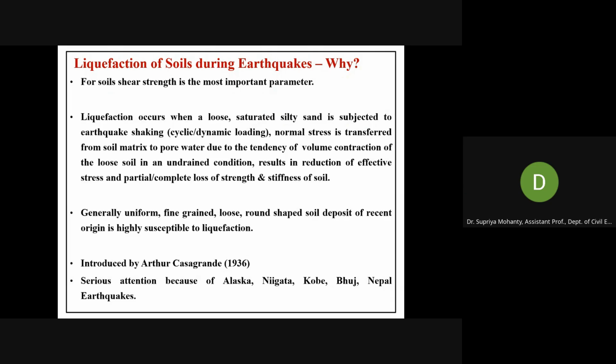Under the loose case, there may be more void space. If there is void space, then the pore water pressure buildup will be more, and it may match the total stress. So these conditions we need to check. Based on our basic geotechnical characterization report, we can see the existing field condition. Depending on the density and gradation, from our sieve analysis result, the type of soil, the density of the soil, and whether it is saturated or not can be classified.